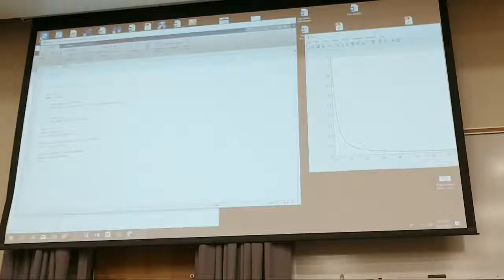And I say that because, do y'all see that, guys? This is now what we get with that cosine. You'll notice it's right at 10. You with me? I didn't adjust the continuous time Fourier transform. I'm just showing you. Now, the minute you see that in the spectrum analyzer, you know your primary frequency is going to be at 10, at omega equal 10, or F is that divided by 2 pi.